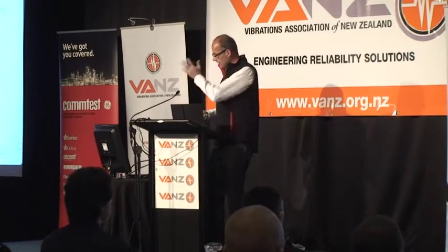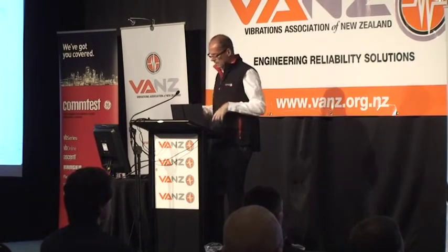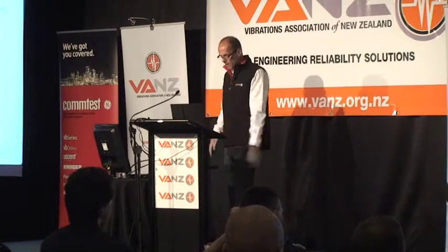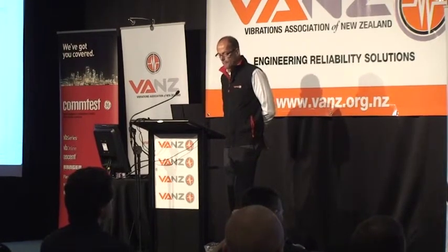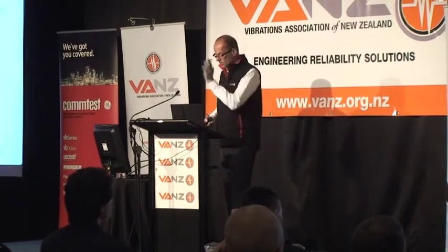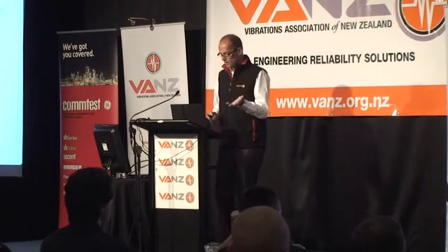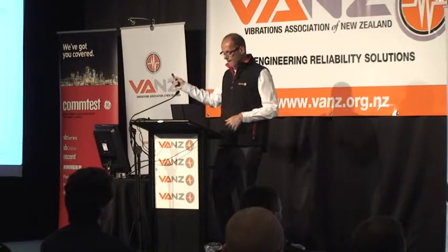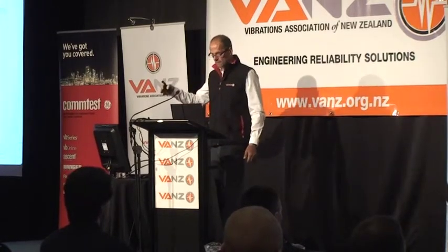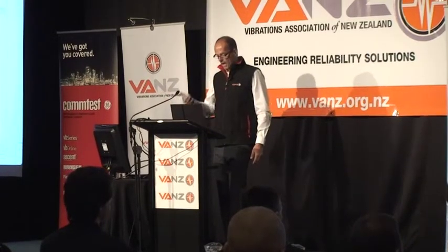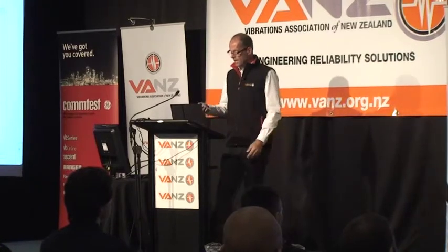And there are these clear peaks that indicate that a fault exists. That was the damage on the bearing. There I'm just seeing these harmonics, as they're called, of the frequency that is related to that, the ball pass outer race frequency. And so we get simple harmonics in that case.